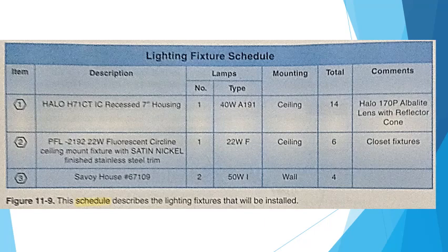Miscellaneous schedules. The number and size of schedules is a good way to determine the size of the project. For large projects, schedules may be included to aid estimating and purchasing. A receptacle schedule and switch schedule may be included. These schedules are similar to a lighting fixture schedule.